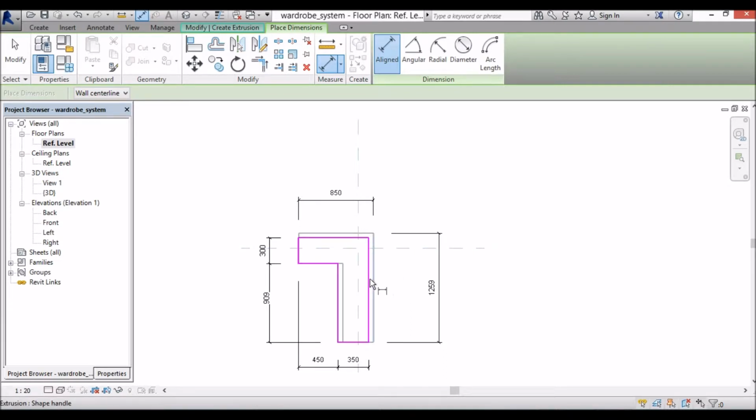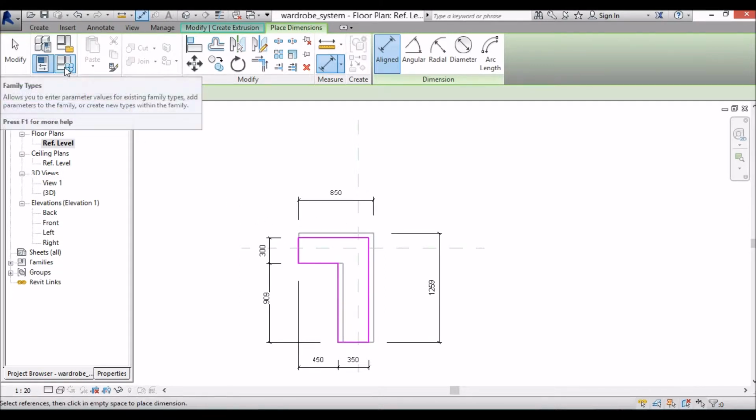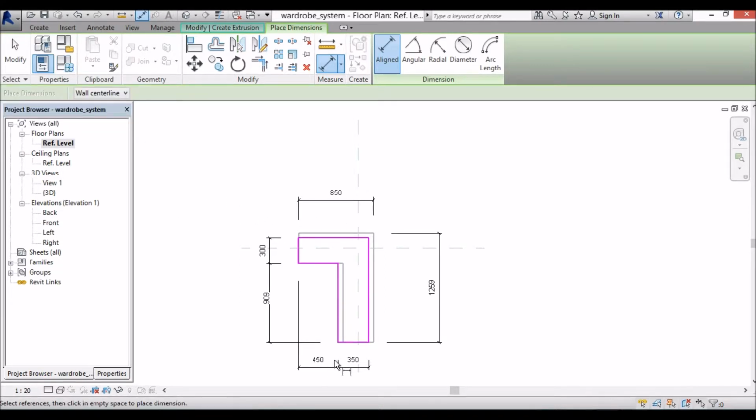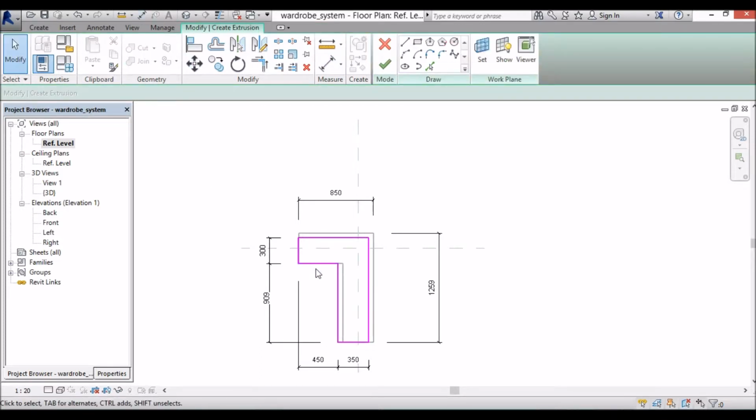So I didn't need to actually go out of this section, and I just had to fix the parameter. That was very easy. So now this line here should actually be 50 millimeters down. So to move that, I'll just press escape, click on that line there and the move tool, and get that triangle up and just move it downwards by 50. Okay, that's much better.